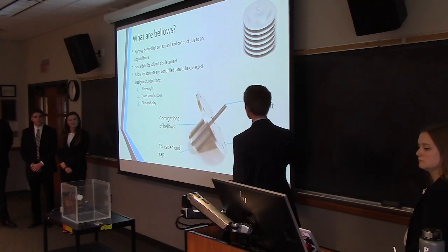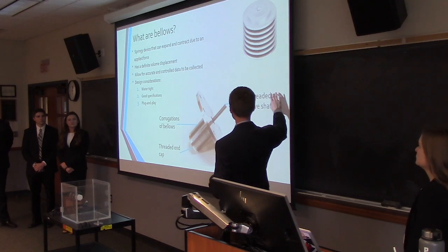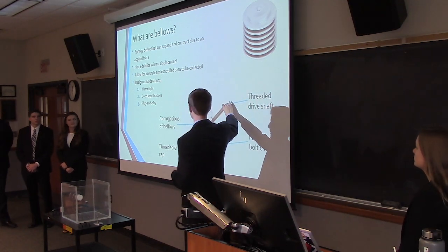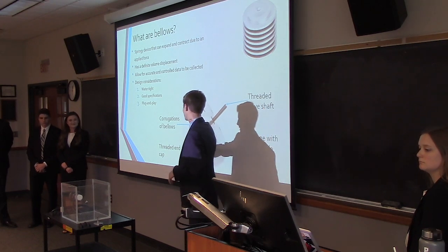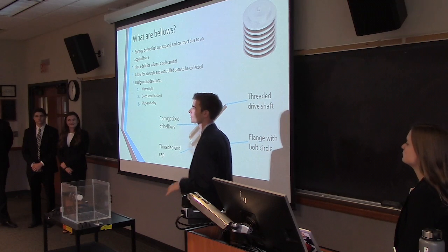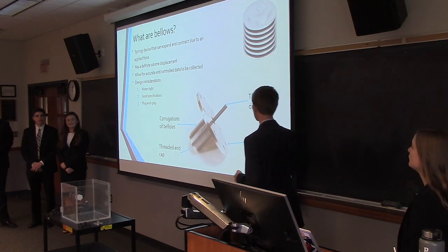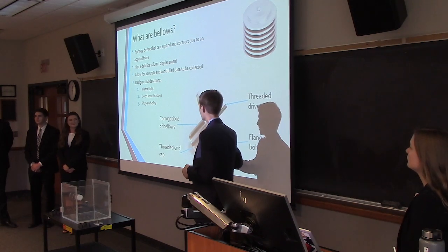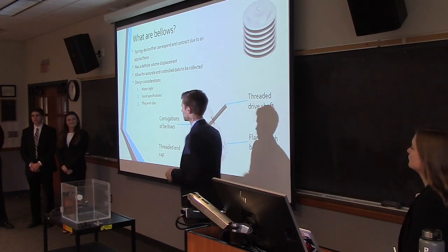So, as you can see from this picture here, there's several important parts. The threaded drive shaft connects to the speakers and is driven by the speakers. This threaded drive shaft connects down into this cap, which is welded shut, and so there's no water leakage. And then this flange with the bolt circle hooks right up to the tank, and these are the corrugations of the bellows that give it its springy-like properties.